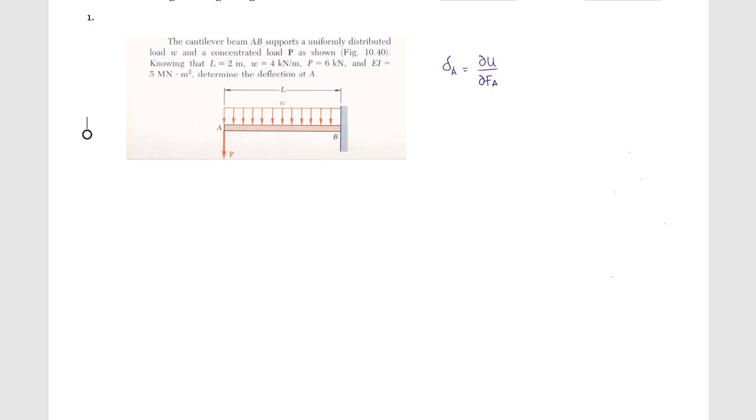And basically all you have to do every time you have a point load is split your integral. So just as an example, if you had another load here and another load here, F2, F3, you would do an integral from A to here, because you can write this as a function of W and P, and then from here to here, because you would be able to write the equation from here to here as a function.